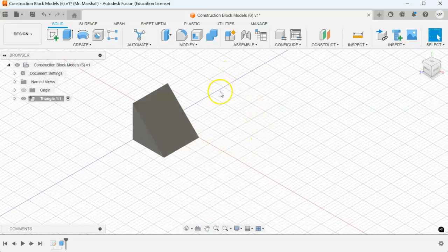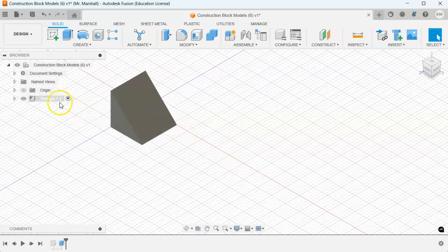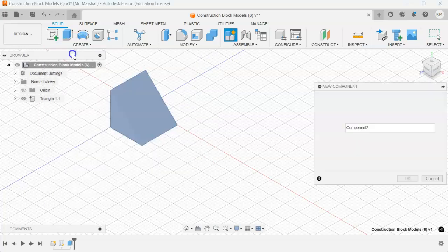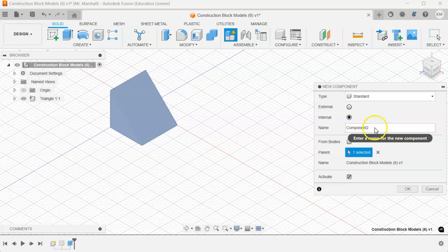Again, we're doing this in a top-down model, so it's really important, and hang with me here, that we go back up and activate, in our browser, the top level of our design file, and then we need to create a new component. This is important for top-down modeling, that we have a different component for every object or shape that we're drawing, so that we can create some 3-view drawings and export some PDFs a lot easier down the road. So we're beginning with the end in mind.